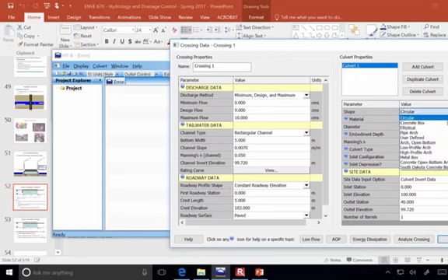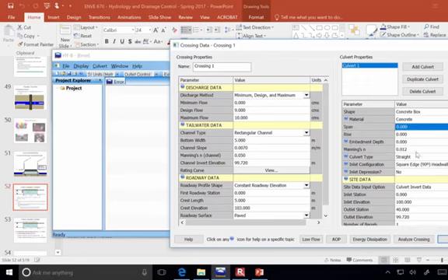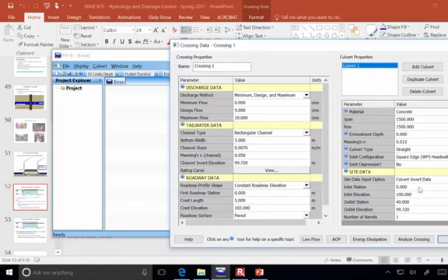All right. So concrete box, we're going to do concrete. I'll change it from 0.12 to 0.13. That means maybe our contractor wasn't smoothing out the concrete as much as we would like. We're putting a little bit of a safety factor there. Okay. And we already specified the elevations and length of the concrete.